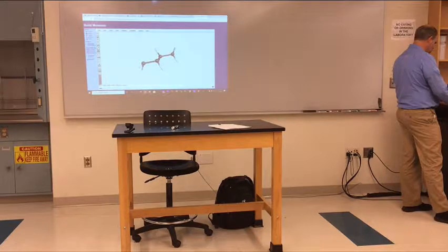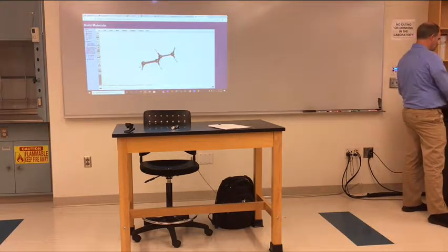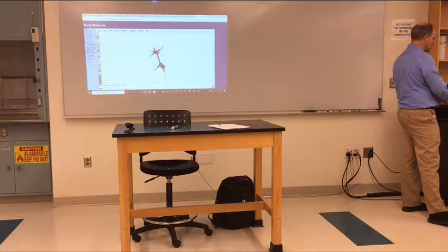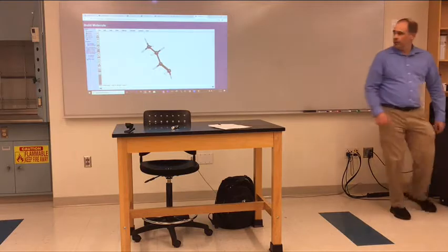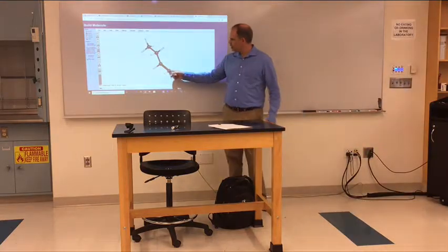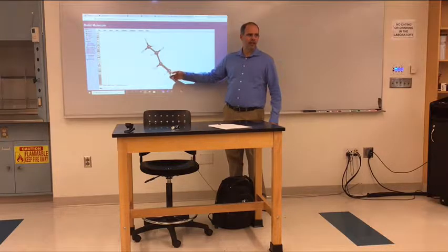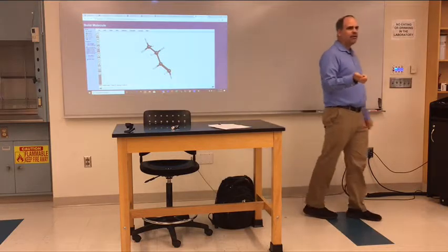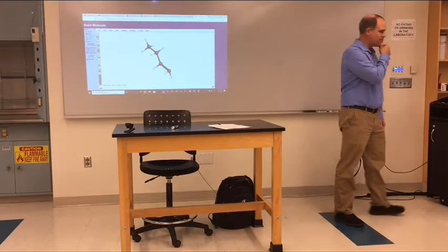We should be able to click on the adjust, no, sorry. Go back to the periodic table, click carbon, and then click on one carbon, drag to the other, and let go, and it made a carbon-carbon double bond. Okay, so let's rotate it around to take a look. But if you look at it, it doesn't look right. The hydrogens on carbon 1, right here, look like they're sp3 hybridized. They should be more planar. So what we need to do is hit that optimize button again to optimize the structure as we adjusted it.